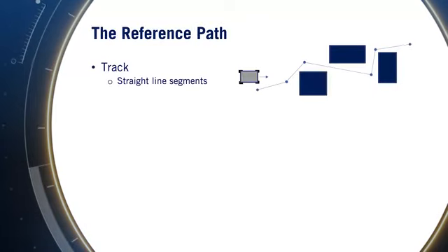The easiest approach is to define a sequence of straight line segments by requiring a sequence of endpoint vertices that are connected linearly. This path definition can be very compact and easy to construct, assuming points are well spaced and the environment allows for mostly straight line motion, as in a Manhattan grid of roadways. However, the path includes heading discontinuities, which make precise tracking a challenge with a steered vehicle.